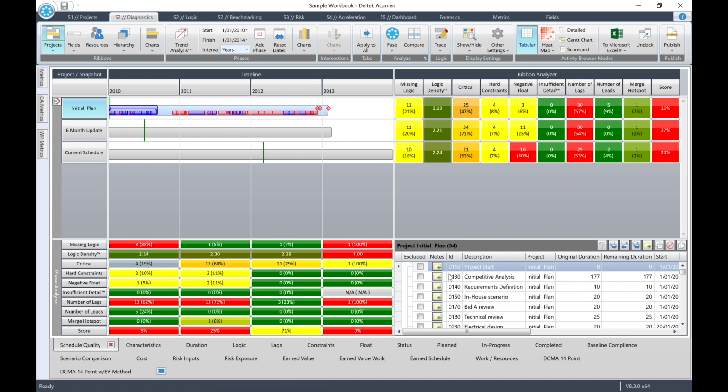To add a note or annotation to an activity, you would use the Notes icon to the left of each activity. So, you can add an annotation to a single activity or multiple activities. You can also add multiple annotations to an activity by clicking the Activities Notes icon again.